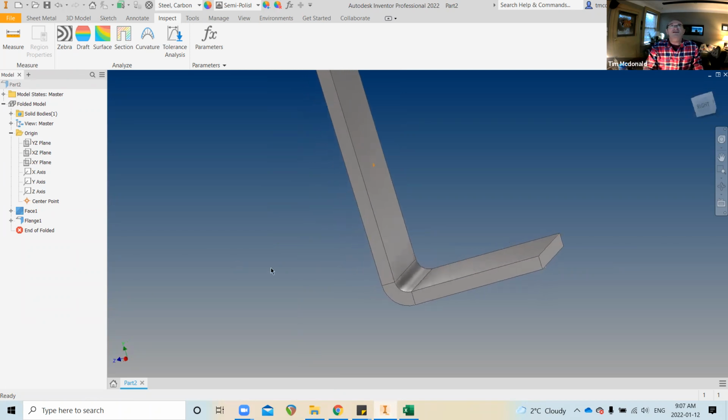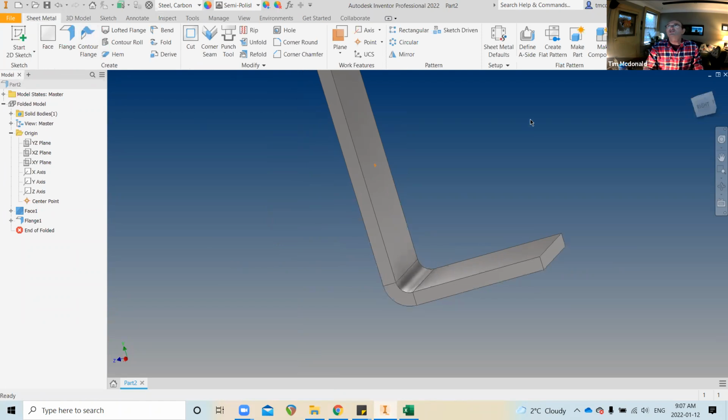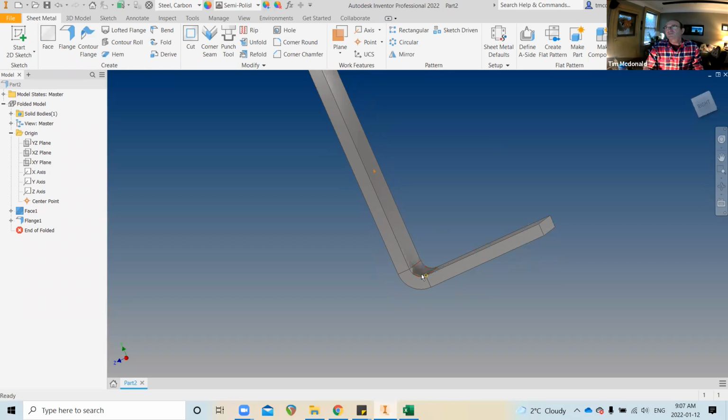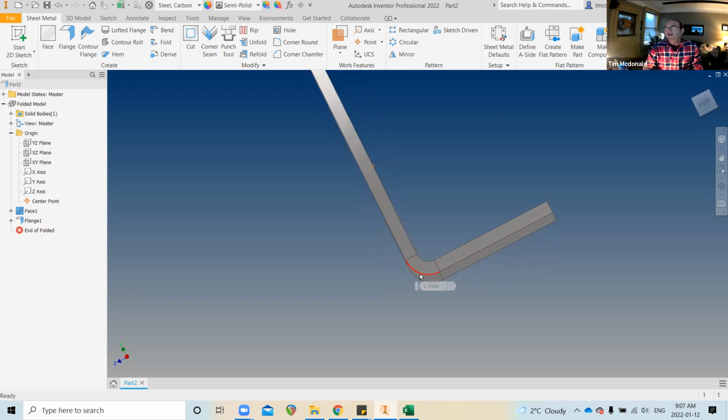Okay, just a little bit of knowledge from a guy who's been on the shop floor long enough to understand within the sheet metal environment, we would rarely, very rarely bend a 1/4 inch plate with a 1/4 inch radius. We tried to standardize in industry to avoid cracks. What's happening here is when I strike this face on the inside where the die is hitting, it's going to compress. On the outside, it's going to stretch. It's going to be under tension. And depending upon the material, you may wind up with cracks, or it might break all the way across. And I have broken my share of steel in my day.